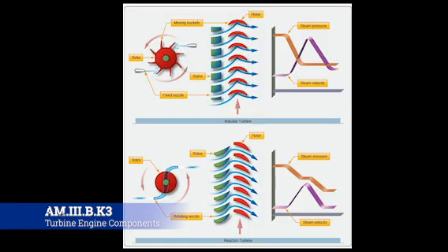All right, now in the turbine section, there are three types of turbine blades. There's the impulse turbine blade, the reaction turbine blade, and the reaction impulse turbine blade. The impulse turbine blade is also referred to as a bucket. It's catching things. This is because the stream of air strikes the center of the blade and it changes the direction of the energy as it causes the blade to rotate the disc in a rotor shaft. So imagine sticking your hand out in a kind of cupped fashion out the window, and you would catch that air. That same backwards push that's happening to you, imagine your body is the shaft and it starts to spin it around.